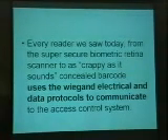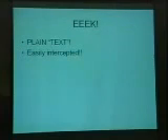And that's a little bit of a problem. It's plain text, pretty much. It's easily intercepted. It's even more easily replayed. You've got your output from biometrics, and that includes the output from your strong crypto readers. A lot of them have Wiegand output on the back. Some smarter manufacturers are starting to move away from this, but it's a huge problem.